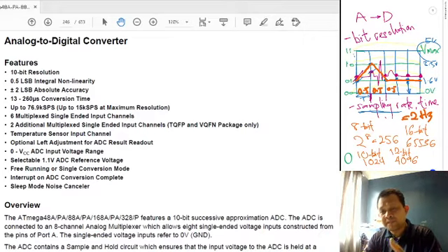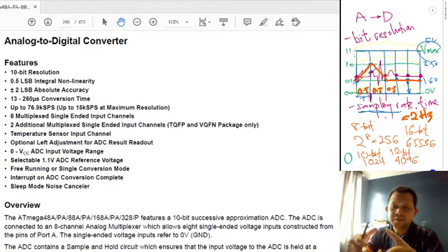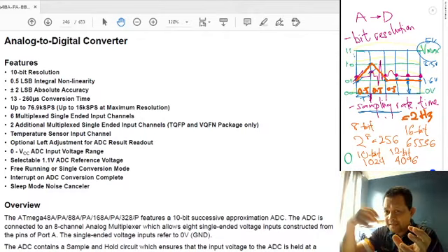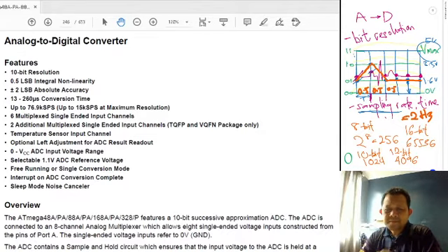Maybe in the future, maybe in the next 20 years, you can look at maybe 48 bits, for example. But that depends on the current technology. Again, you can have many bits of resolution, but you need more memory to do that. More memory means more cost, and you also need to expand your space on the microprocessor board. You need physical space to put the memory ICs on your board.